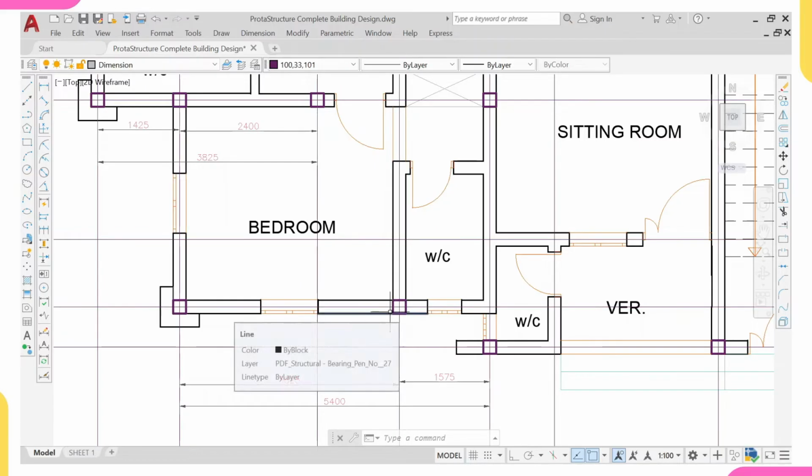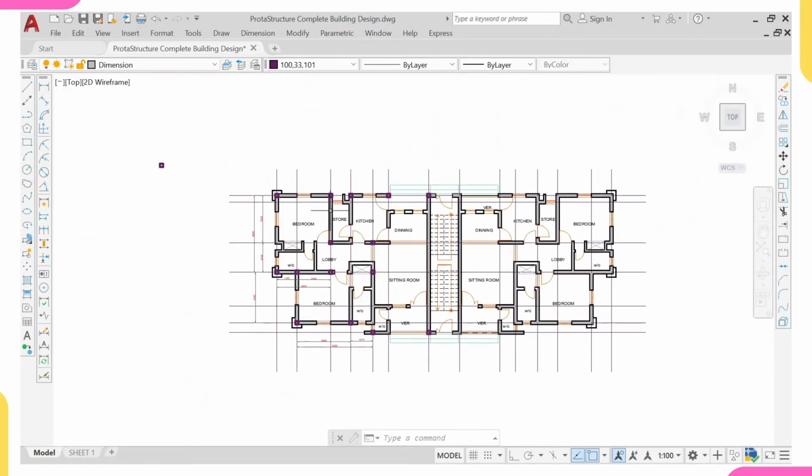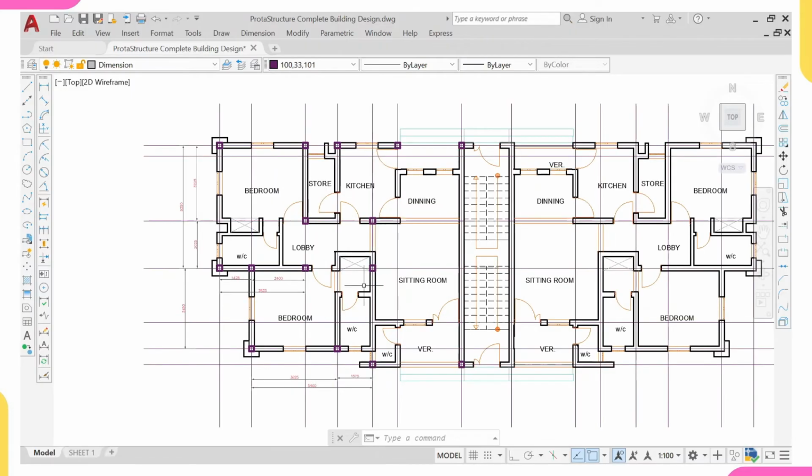If you check the cost, because a column consists of 4Y16 and concrete, you see that he is making profit, but he doesn't know that he's making profit. He thinks that he's making a loss. Because even if you place 40 columns here, they will not ask you any question about it. But once you start having 3Y16 in your beam, they will start thinking, hey, this guy doesn't know what he's doing. But if you have a column at every joint, they will not consider it as anything. That's just the thing, so you have to explain to them.